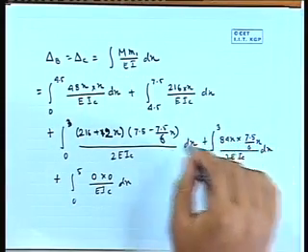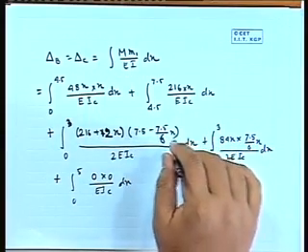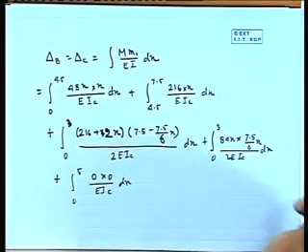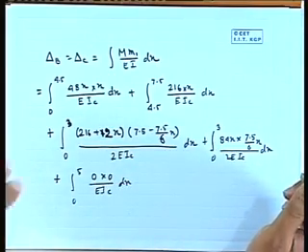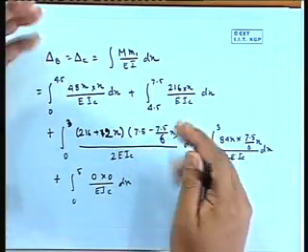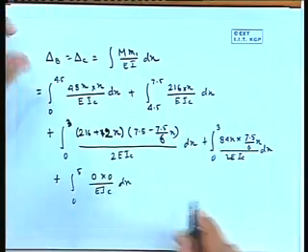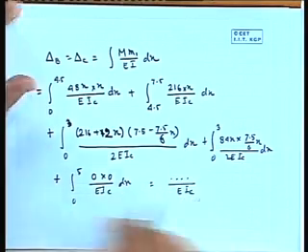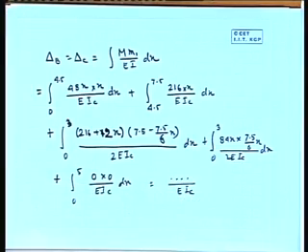Similarly it will be x square, this part you have to simplify, one term will be x square, another term will be x, another term will be without x. So if you perform that integration, you will get some numerical value divided by EIC, right. Now if we put some numerical value for E and IC, we will get some actual numerical quantity for the value of deflection at B and C,